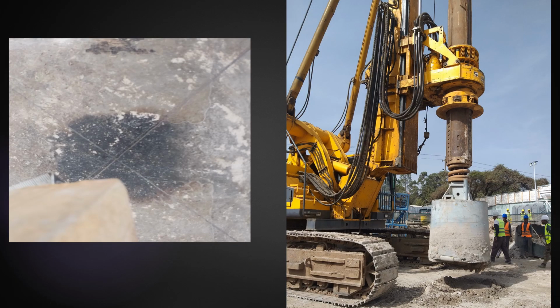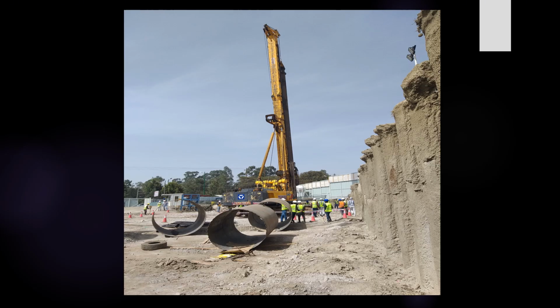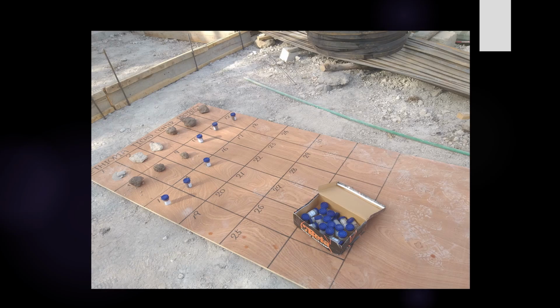And then here, as you can see, this is the mast, or what we call the rig machine. At the bottom of the rig machine, we always check our center is in good hands. This is the bottom of our mast. And then we attach our boring teeth to the machine, so that we can bore and excavate our pile. So these are what we call different casing dimensions for different piles. So we are going to commence and excavate.